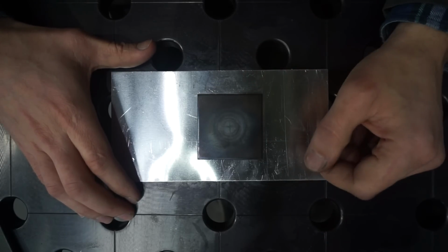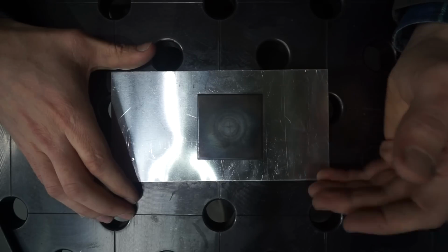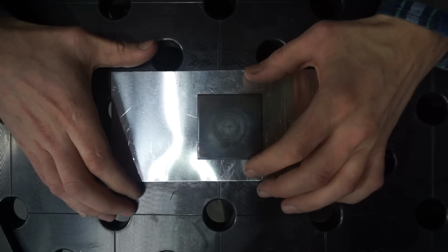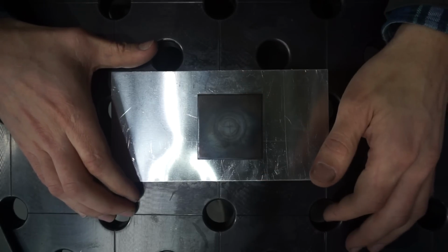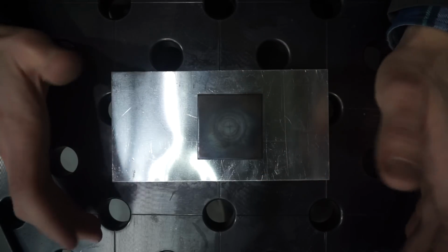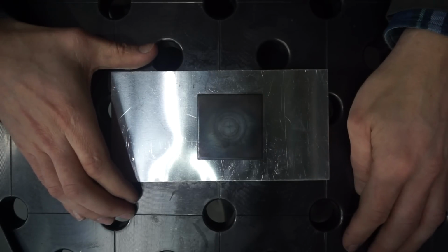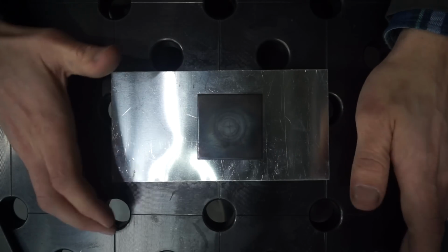You can try for yourself. Thickening will continue with even consecutive heats up to a certain situation. Before that, probably surface scaling will inhibit a reliable thickness measurement, but you have to try for yourself. This is the fourth and final essential observation on welding distortion of this episode.